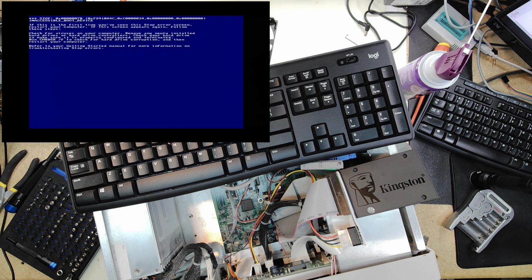And my guess at this point, as I'm going through the troubleshooting process, is it's probably a difference in the disk controller drivers between my 1680A and the 1680AD. Maybe it's a different motherboard. I haven't tried to look at the detailed specs of the motherboards, but I think Agilent used a handful of different ones in the 1680s. And so it could be that this motherboard is using a different driver. That Windows 2000 image that I'm using from the other computer probably doesn't have the proper driver on it. And so when it tries to boot up here, it fails.